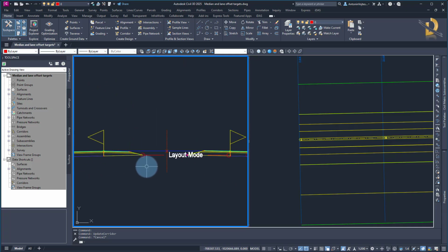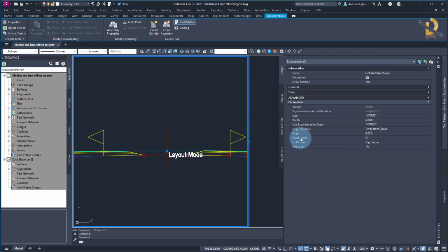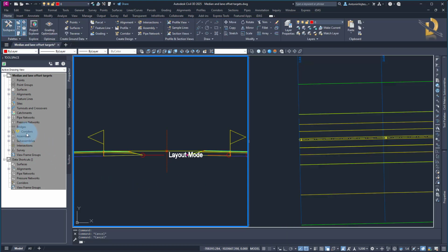And in fact, once you finish with your modeling, you should change those links to have omit codes for point and link. Select both and go to Properties. And for the point code, use omit. And for the link code, use omit. Enter for both. Rebuild the corridor.